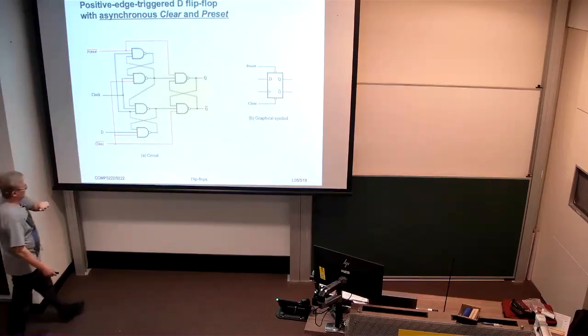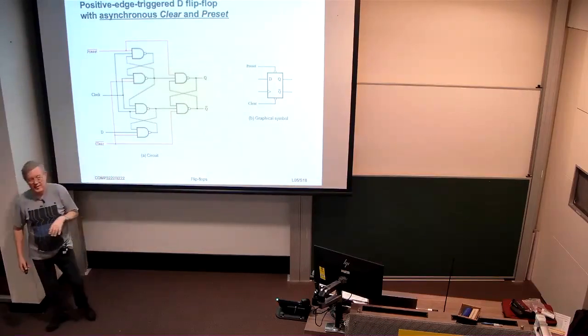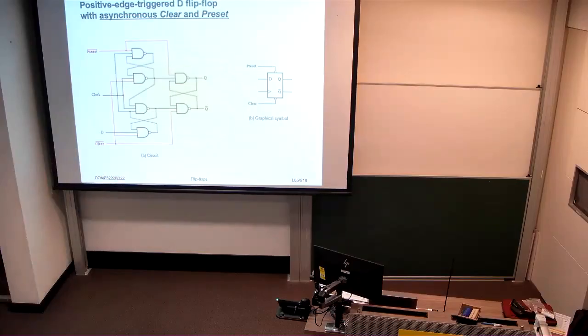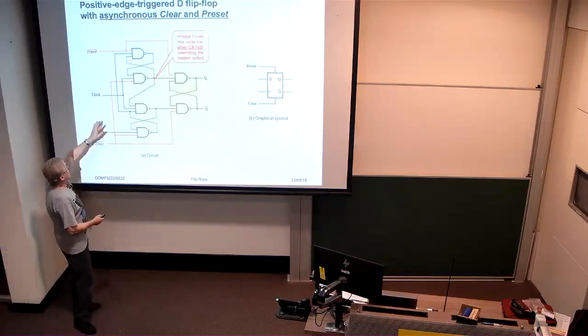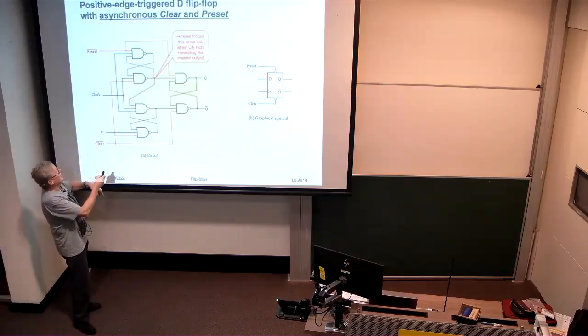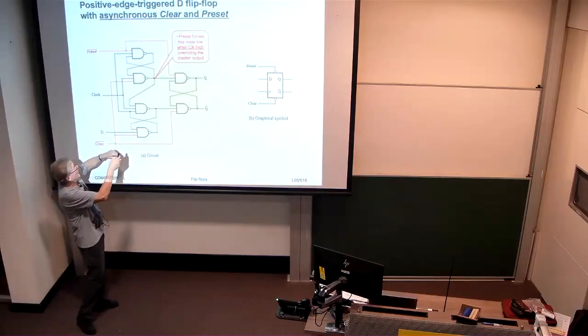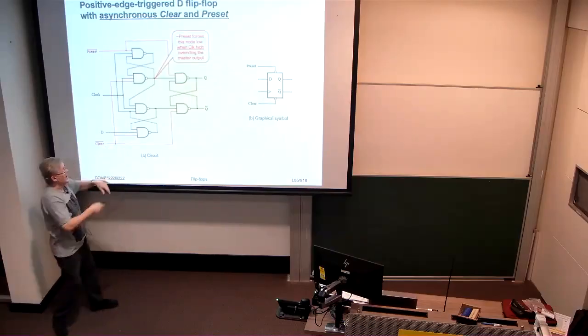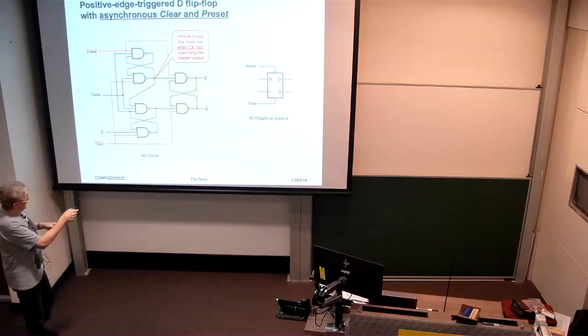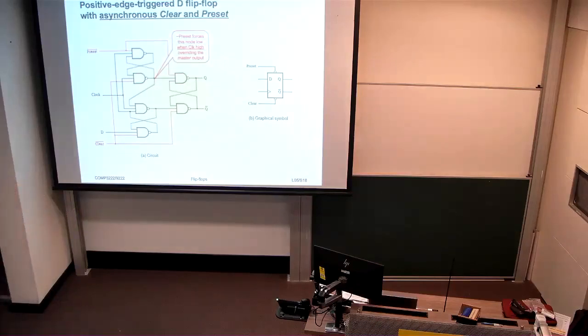For the positive edge triggered D-type flip-flop, it's a slightly more complex arrangement, a bit of asymmetry here between the clear and the preset signal, but essentially the same arguments follow. So when the clock is high, remember that these 2 points are sensitive to whatever the input is and the value that's the output of this NAND gate, to determine what the value should be on that wire.